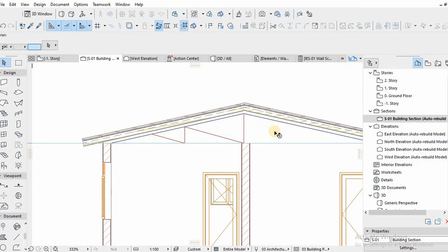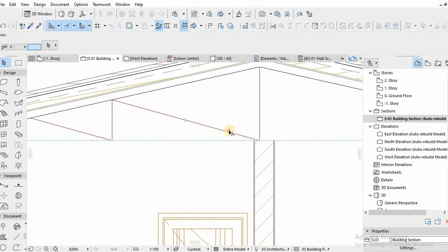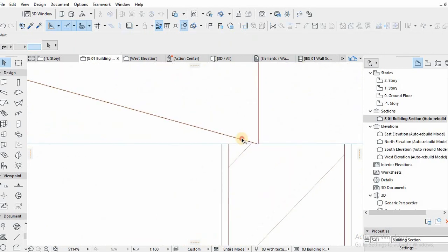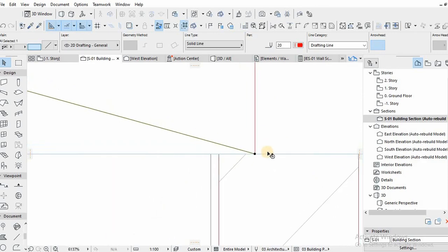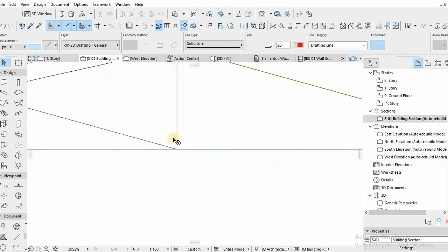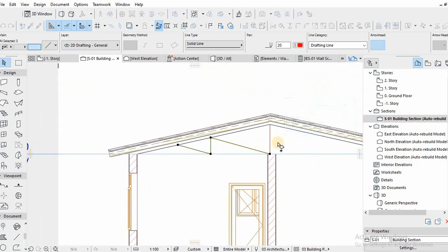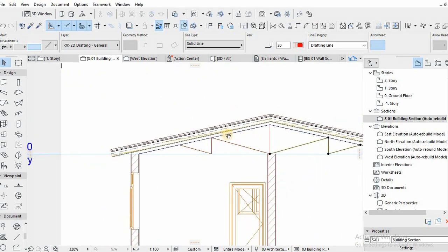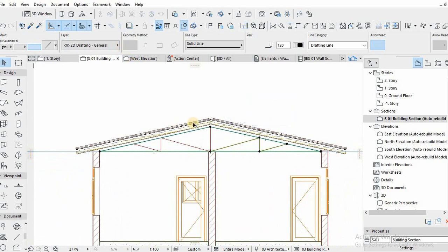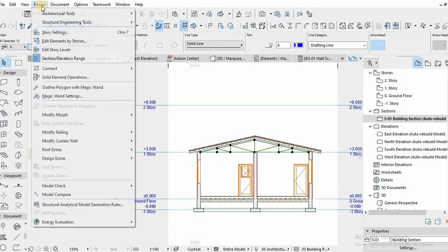I'm going to create my line profiles, to differentiate the lines with different colors. Remember that. And then I'm going to select them, select the framework, and then choose to create truss from the truss maker: design, extras, truss maker, and then that's just it.